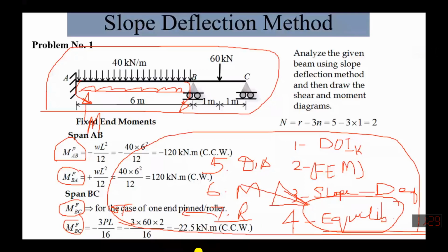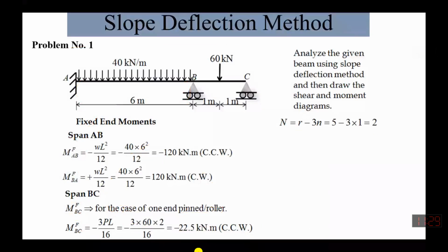Yes, sir. So what is the difference between these two methodologies? Now we'll go step by step. First, we need to find the degree of kinematic indeterminacy. So we'll find that the rotation and deflection here are 0, and there will be only 1. So actually this will be something like this. Normally it goes like this, it's the deflection shape. We are concerned with only theta B. So this theta B is of our concern now. We need to calculate this.